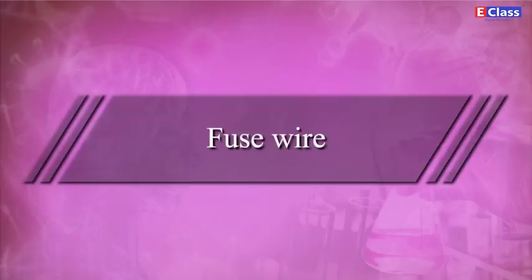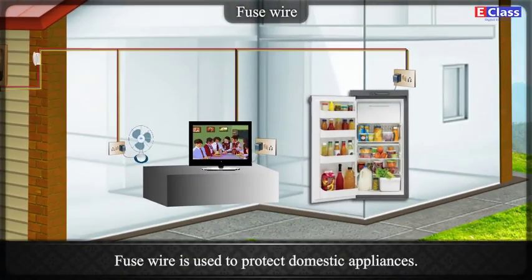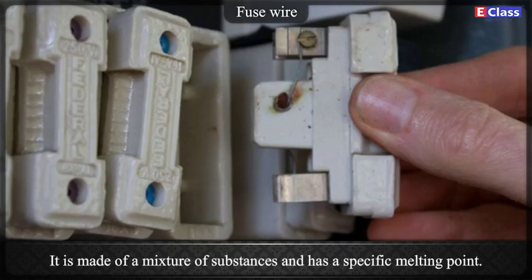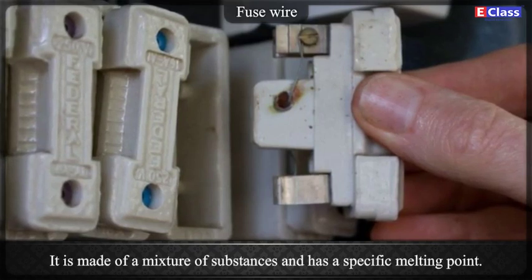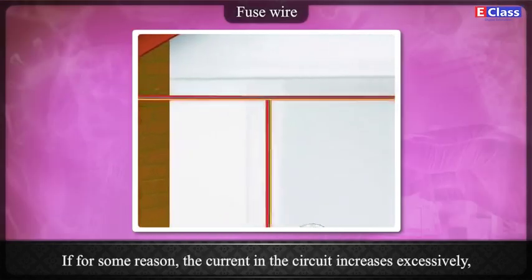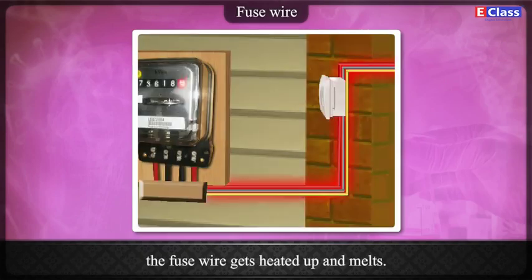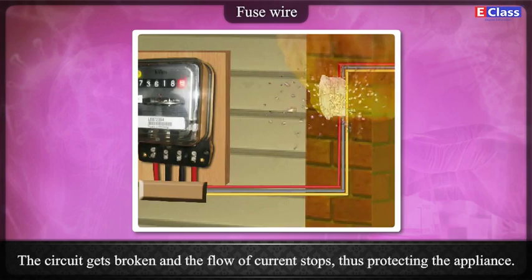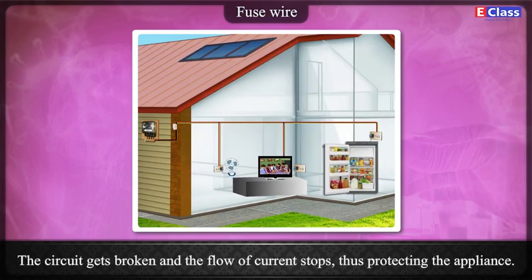Fuse wire. Fuse wire is used to protect domestic appliances. It is made of a mixture of substances and has a specific melting point. It is connected in series to the electric appliances. If for some reason the current in the circuit increases excessively, the fuse wire gets heated up and melts. The circuit gets broken and the flow of current stops, thus protecting the appliance.